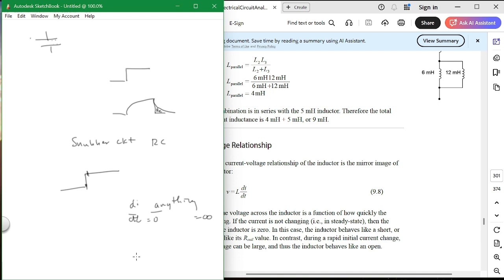In other words, you try to simulate this. So V is equal to that. You're picking it up, and a little switch on the bottom activates, which basically gives you a very high value. It tries to make that current go like that. Okay? And that gives you a shock. You say, so I got a shock because of the inductor? Yes. You got a shock because you drove the dt to 0 or close to 0.